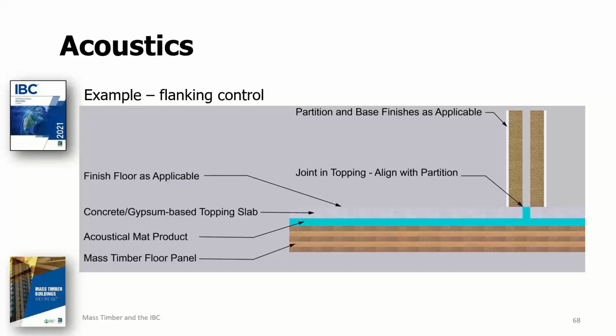The primary way to control flanking is to close all the air gaps. In the context of the three methods noted earlier for improving acoustical performance, vibration isolators can also act as decouplers. And with airtight connections, interfaces, and penetrations, a mass timber building can be designed and constructed to meet acoustic performance expectations. Several detailing and panel layout techniques exist that can help minimize flanking.